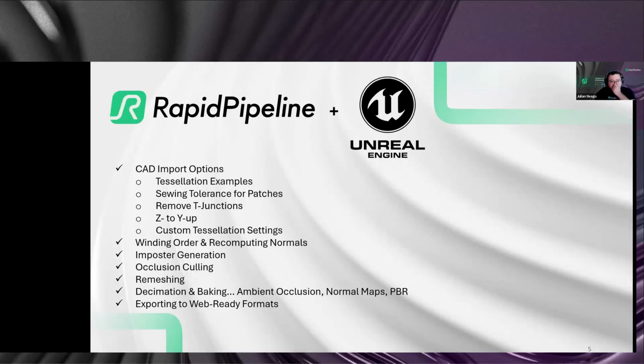Today I will go over all the options in the import pipeline in terms of CAD data, and a few little tricks here and there, such as sewing of the BREP patches coming from CAD. Sometimes that's really helpful, for example with automotive assets, which usually come split into a lot of different smaller patches. It's sometimes tough to then merge the vertices by distance or do some kind of post-processing operation like that. It's a bit like editing a JPEG on the 2D side: you don't really want to do that. You want to fix that on the BREP, on the parametric solid level, before doing the tessellation, and then have cleaner vertices and clean connections. We're going through all these features live in the plugin.